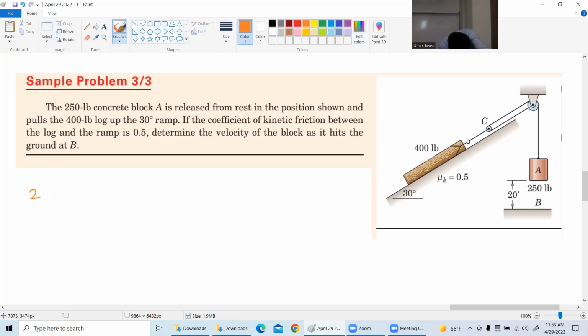2T equal to 0.5 N. I will make the free body diagram, please give me one minute. Plus 400 sin 30. Okay, and T comes out to be, I will explain this to students, 186.5 pounds.